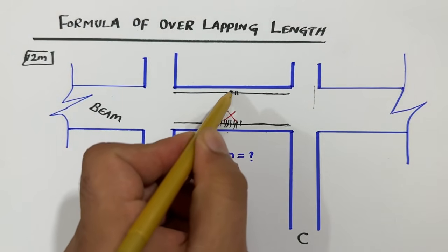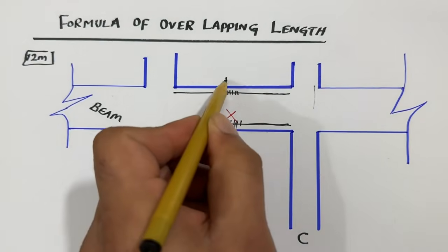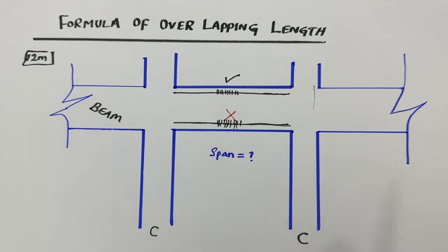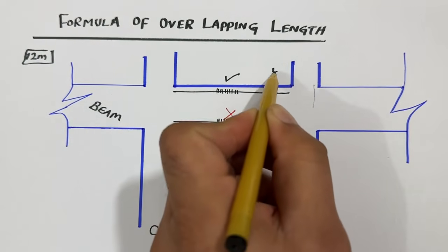So remember in this point guys, the lapping is allowed at the top portion at the distance of mid or L/2. So this is the place to provide lapping length, otherwise you can't provide, right? So try to provide the lapping after L/4 distance. Guys, you can see L/4.